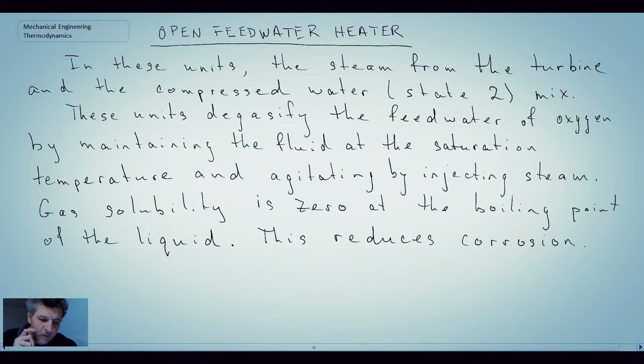So with the open feed water heater, what we're doing is we're taking steam from the turbine and we're mixing that with the compressed water at state 2, and the mixture is coming together. Another thing that the open feed water heater does is it helps degasify the feed water.